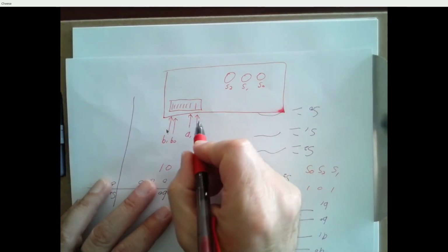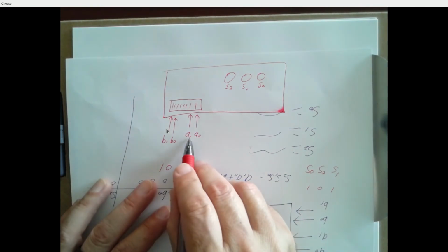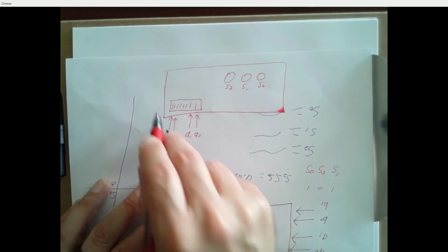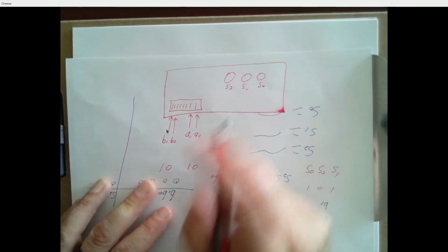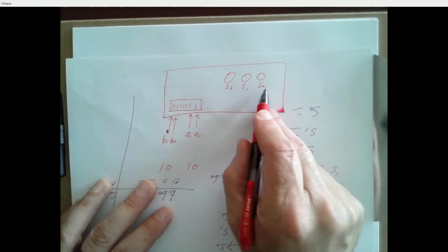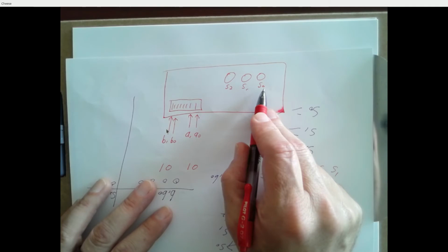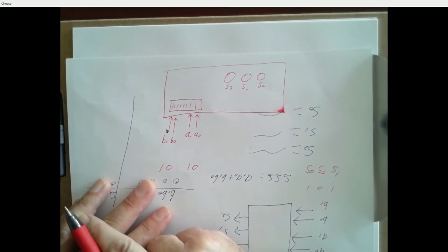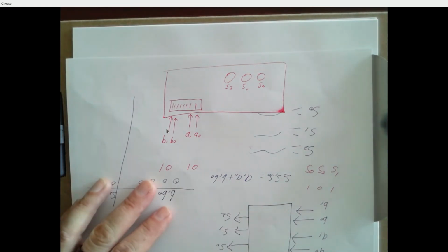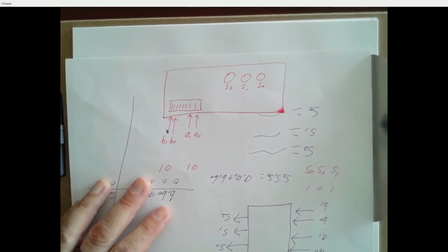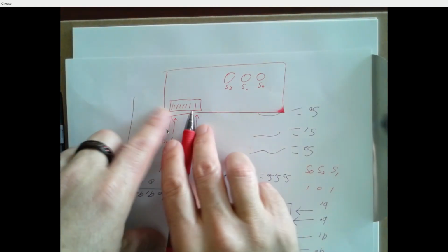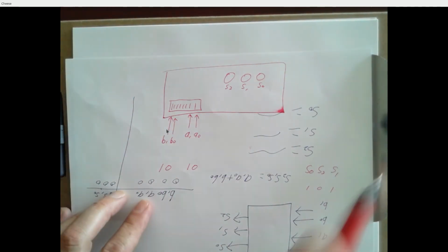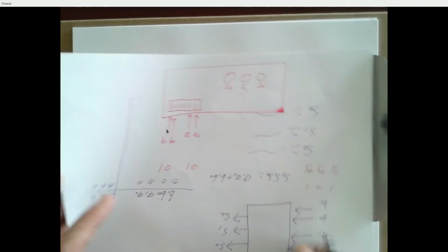Lay your switches out like this. 2 rightmost ones, use most significant bit, least significant bit. 2 leftmost ones, most and least. Lay out your LEDs in order, most significant, least significant. Guarantee it'll save you time. I'm not making it a requirement this time, because inevitably some people won't do it anyway. But it will definitely help you out. Having these switches on opposite ends stops you from accidentally hitting one when you're hitting the other, and so on and so forth. So that's a suggestion.